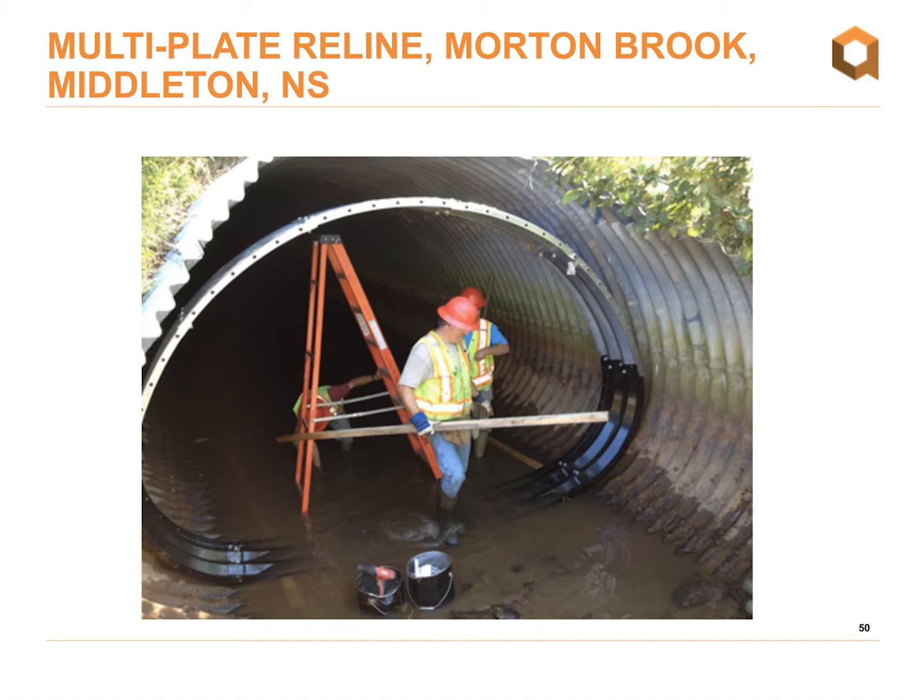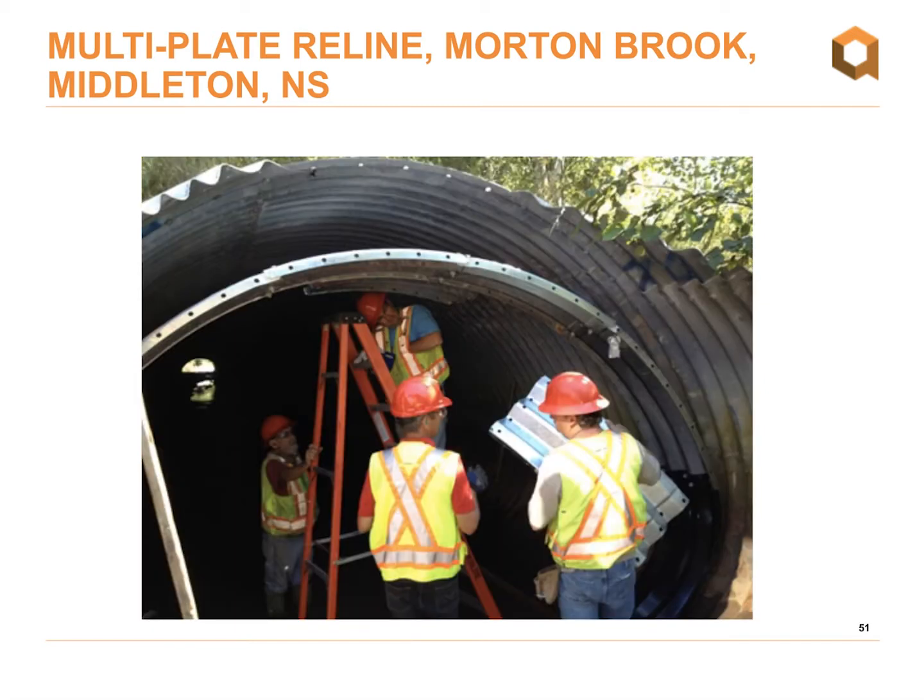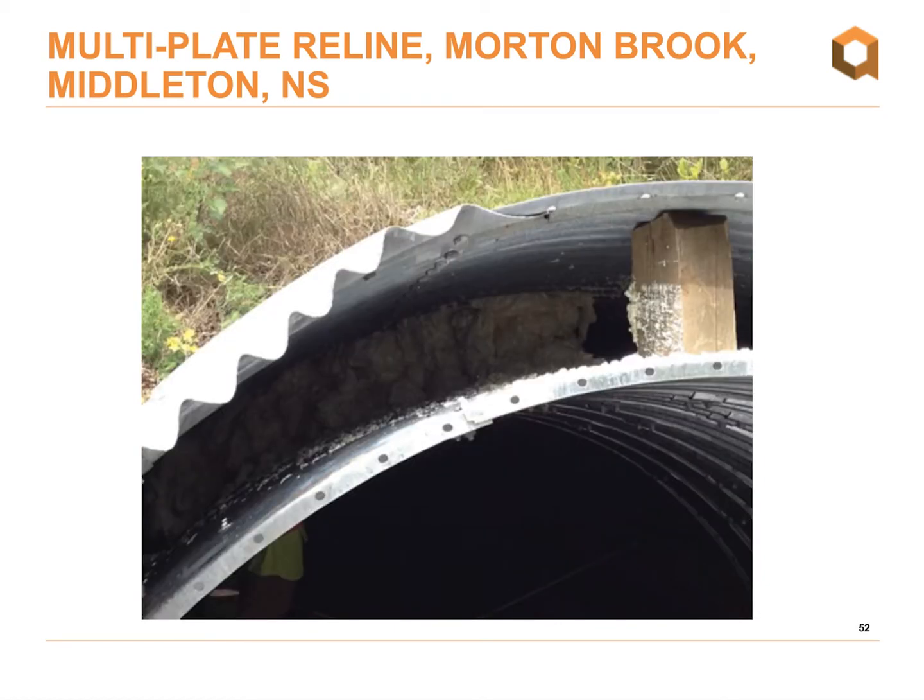And once the first ring was completely assembled, successive plates and rings were connected until the entire structure had been assembled and torqued. So as shown here, no heavy lifting equipment was required to assemble the tunnel liner plate, as each segment is easily handled by one worker. Blocking was placed between the crown of the new tunnel liner plate and the host structure to prevent floating and movement of the structure during the grouting process.